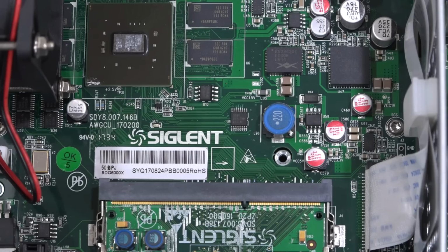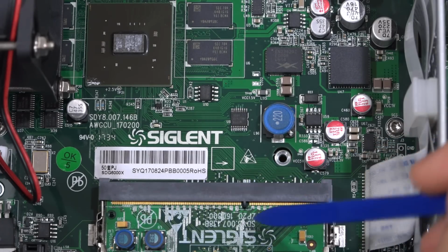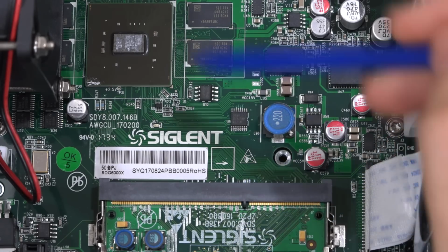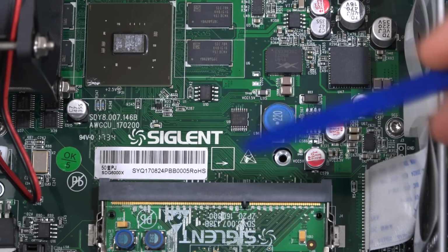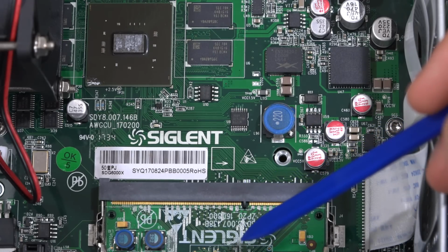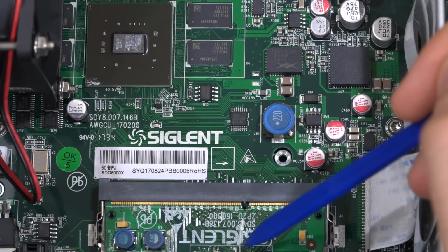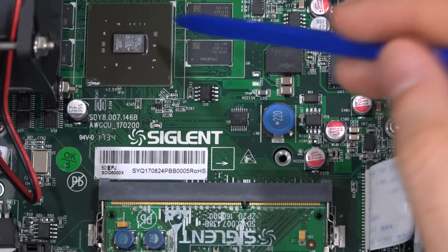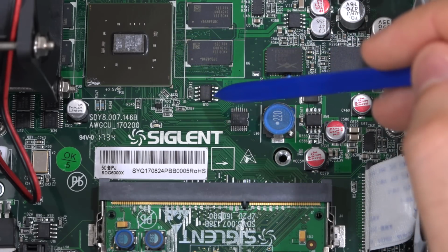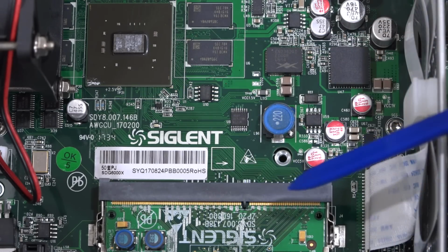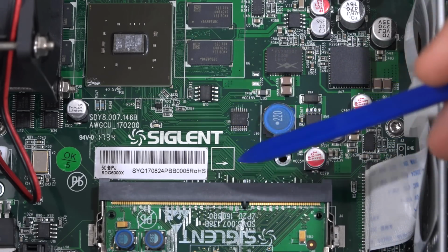there. So here's the top of the card for our application processor, and you can see there are high-speed traces between the main processor and our FPGA. Now, this is to be expected because you would need some fast interface to transfer the computed waveform from the main operating system, however it is generated, either through receiving it through the USB or Ethernet or internally computed directly to the FPGA, which can then be stored onto memory and then played back, and I will talk about that in just a second. So having these high-speed interfaces gives us an insight on how they have divided the computation task for waveform generation.